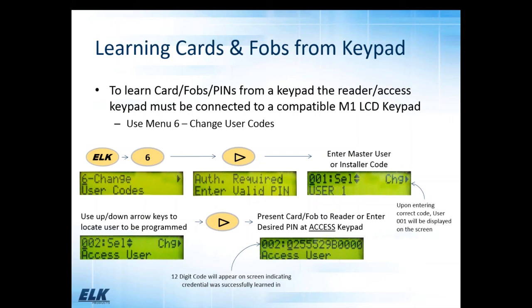One question we had: does a garage door opener or gate opener count as a door? As far as an output being taken up off the system, it would take an output for each one of those things. But as far as the door count is concerned, the number 16 is based on the number of keypads or type 1 devices that the system can support, which is 16. That's a combination of your keypads, access modules, or supervised power supplies. So that's where we come up with that number.